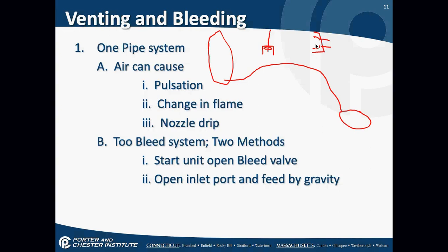There's no way for it to leak unless you make a bad flare. So the only type of connections that you're allowed to use in an oil line is flare fittings. You may not use compression. It has to be flare, because compression fittings leak.